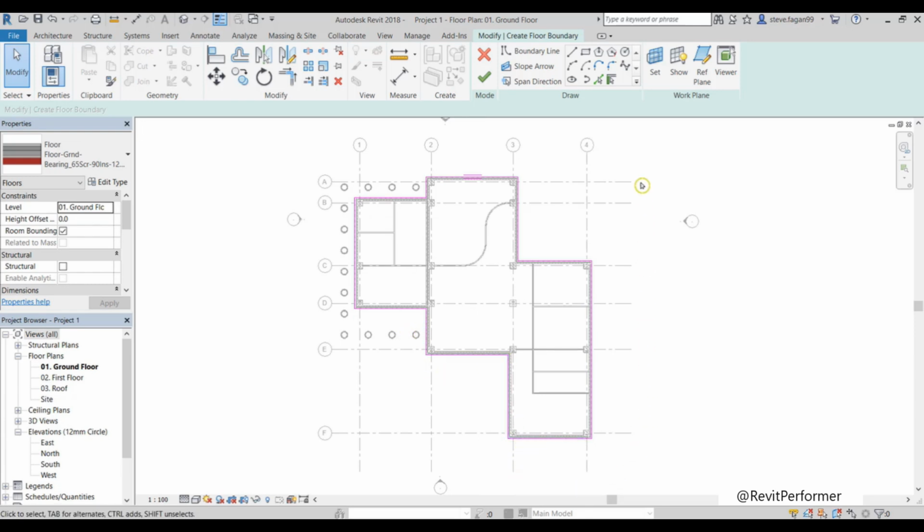We now have to draw the outer side to create our footpath. You can also open up the PDF 007 path. The path itself is going to be an offset of 2 meters from the inner boundary. So if we use the offset tool in the modify panel, we can change the offset number to 2000, pressing enter. And I'm simply hitting the top, right, bottom, and left. I'm not going to do each individual segment, because I'm going to use my trim and extend to tidy up those corners, saving myself a bit of time.